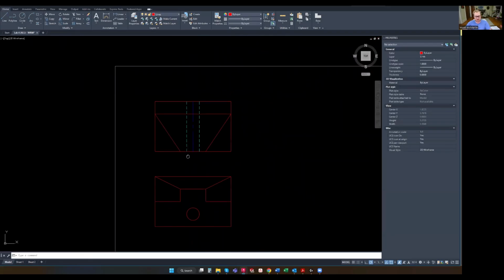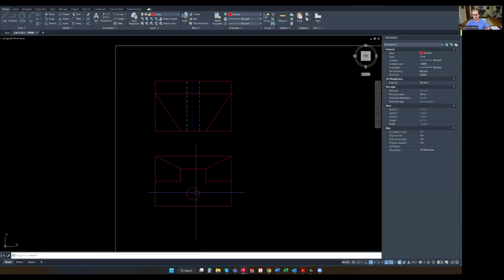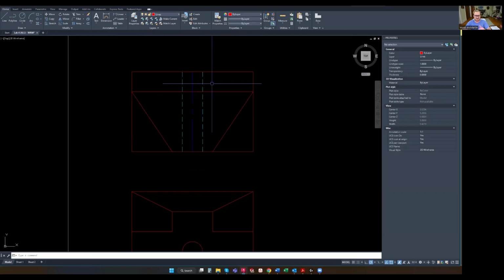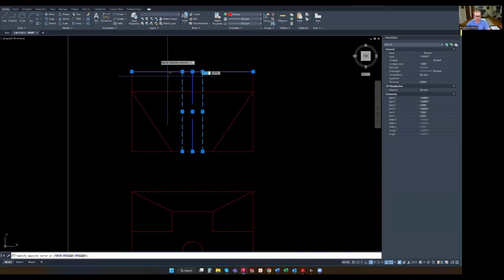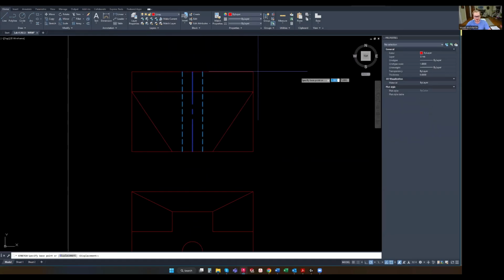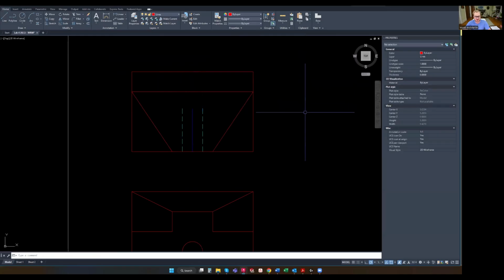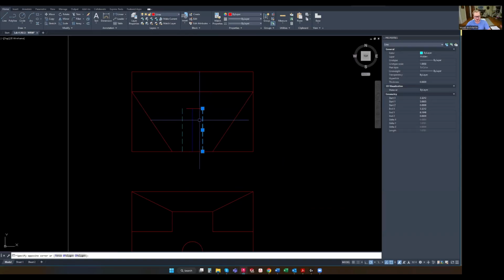What those hidden lines are showing is, if we see from this front view, this hole goes all the way through this part. If it didn't go all the way through, hypothetically, if we just had something like this, we could show this stopping. I didn't draw that all the way, but you get the picture here.